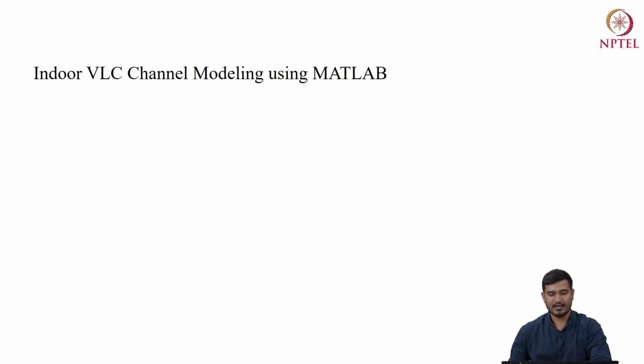So going ahead, we are going to simulate the indoor VLC channel model, indoor such as an office room or factory environment. You can change the room dimension. The first thing that we are going to simulate is received power analysis. With the help of received power, you will be able to plot the bit error rate, outage probability, and the delay spread analysis.